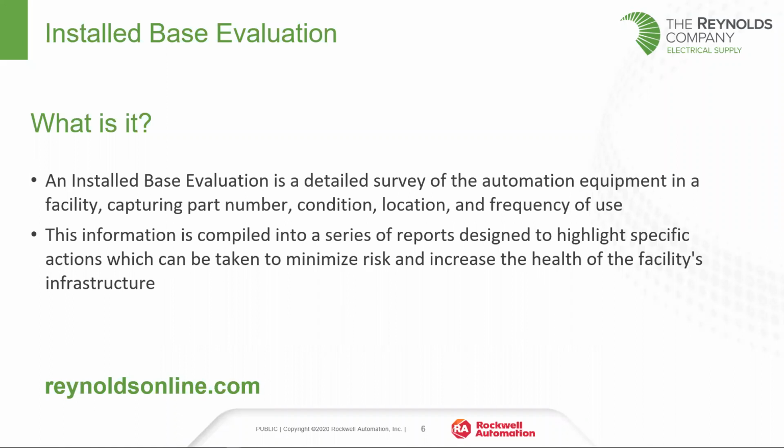So what is it? An installed base evaluation, or IBE, because acronyms make everything easier and they always make things more clear. The IBE is a detailed plant survey. We're going to come in, look through your facility, look through all of the control panels, and then come back with a whole slew of data for you. We're going to be looking at what part numbers you have for everything installed in there, so you have a full bill of materials. What condition are the panels in? Where in the plant are they? How frequently are they used?